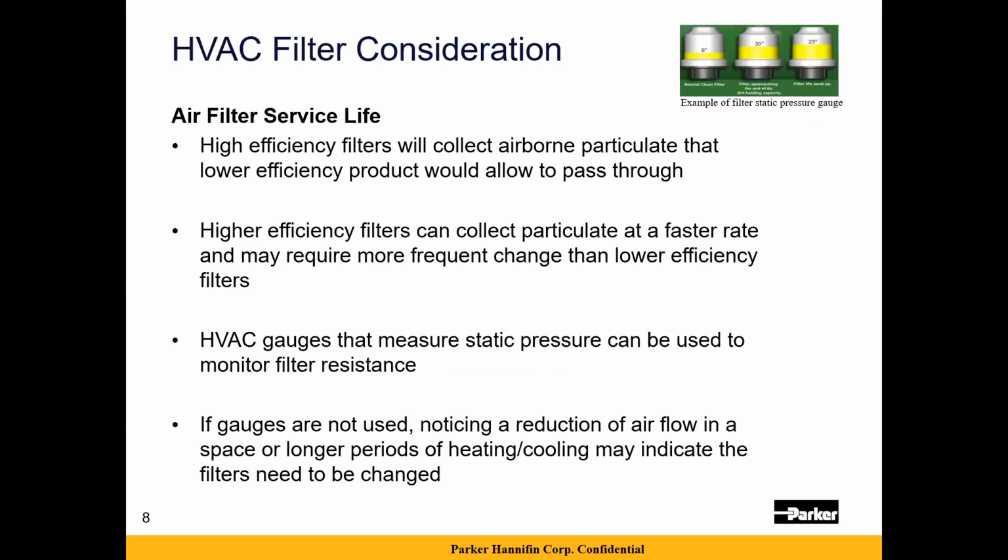Finally, air filter service life. With higher efficiency filters, they will collect particulate at a higher rate than what a lower efficiency would see. So it is possible that that higher efficiency filter could get to its end of service life faster than a lower efficiency product. It's essentially doing its job by catching that smaller particulate, but again, it loads faster.